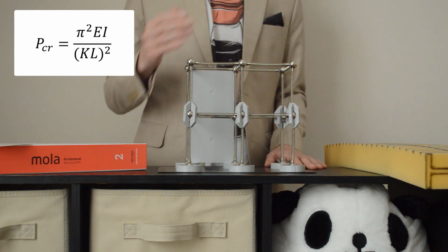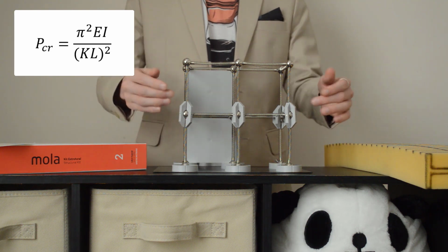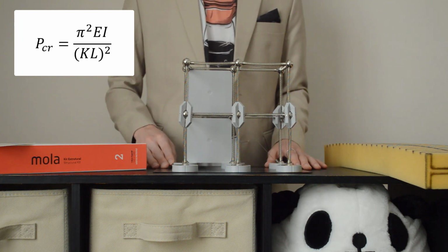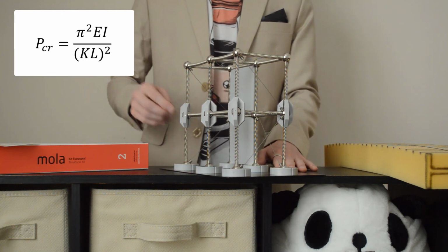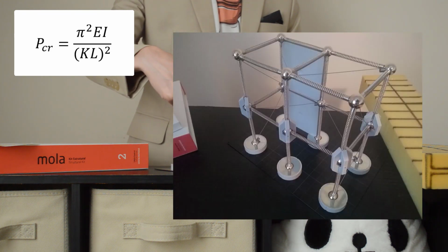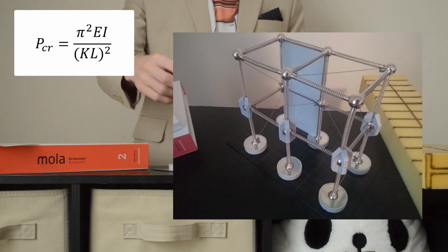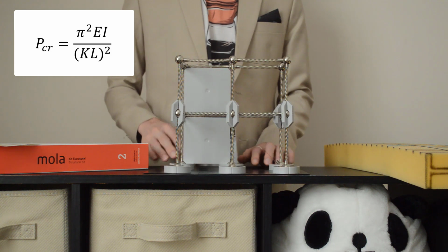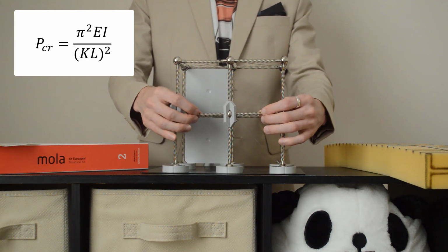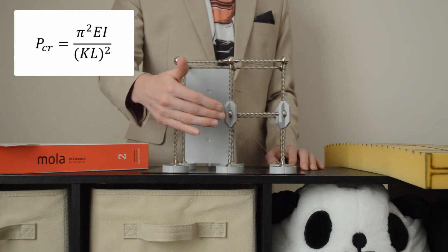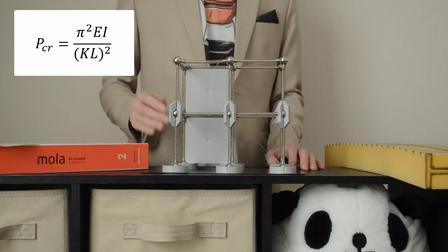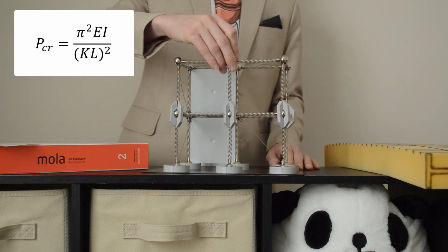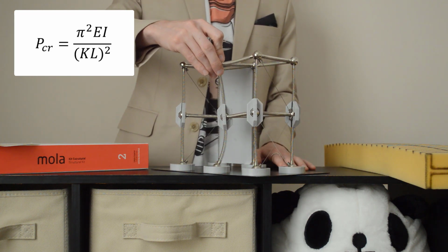Now, let's compare that to the interior column here. As you can see, it does have beams framing into it in this direction along the long side of the building. However, if I turn it this way, hopefully you can see that there is no beam in this direction. So there is nothing bracing this column in and out in this direction. So the question is, is this brace here enough to cut the unsupported length of this column and increase its capacity like it did with these two? And of course, as we saw earlier, it does not.